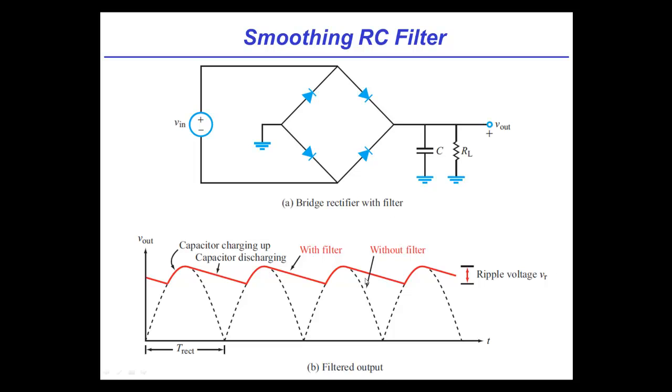That makes sense. Now we're going to come back to this exact circuit afterward, and we're going to teach you how this is actually a filter in the formal sense. And we'll show you how, once you recognize that this is a filter in the formal sense, this waveform would have been filtered to look like this. But in the time domain explanation, it works just as well. In other words, this thing can't discharge as fast as this wants to, so it just sort of coasts along.